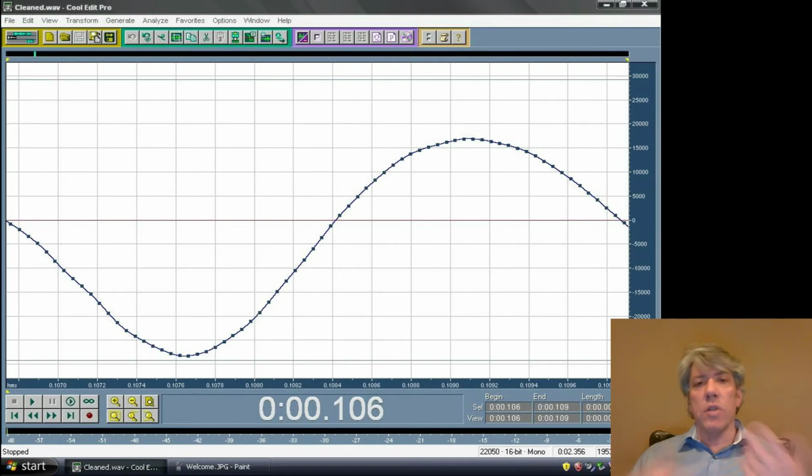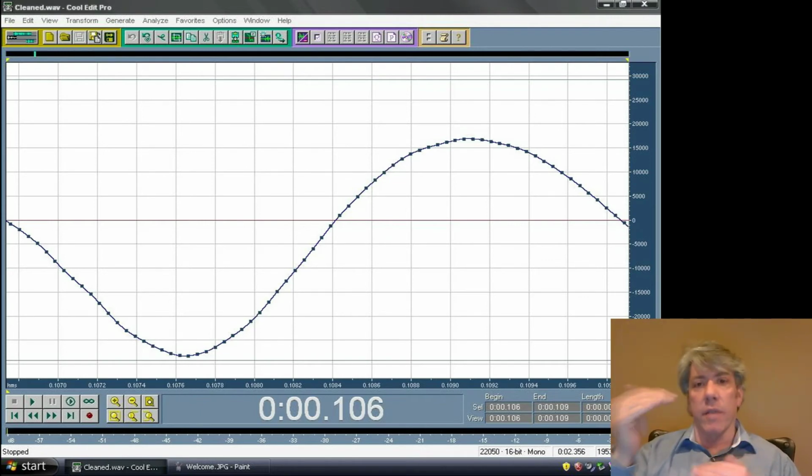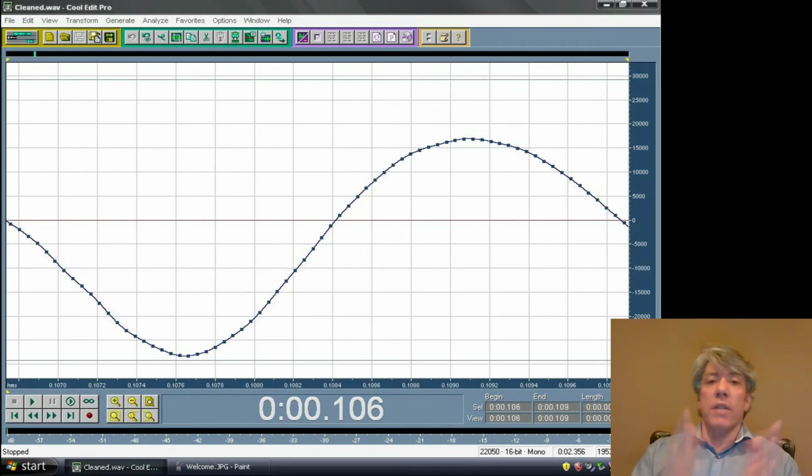Now let's change it just a little bit and say that I don't want to measure 0 to 65535 in temperature. That's a heck of a temperature. I want to measure to half of that, which is still a heck of a temperature, but 32,767 degrees Fahrenheit. But I'm going to do it with a 16-bit number still, so I still have from 0 to 65535. Well, now each degree would be 2 number changes. So you can measure down to a resolution of half a degree Fahrenheit with that.